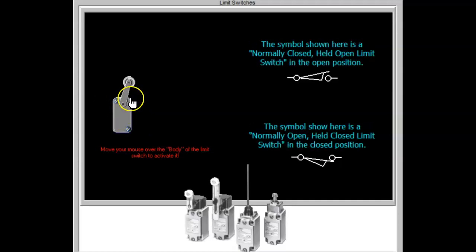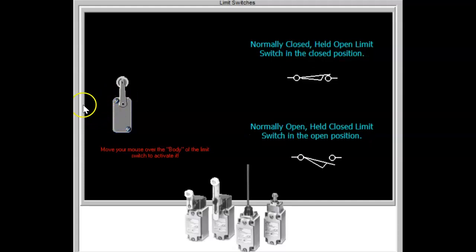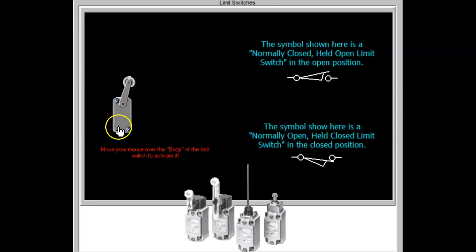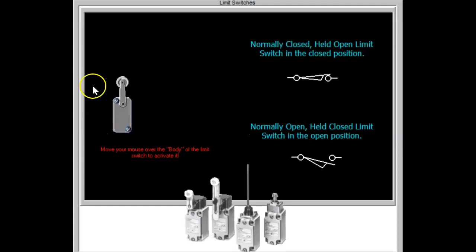Generally, the operation of a limit switch begins when the movement of the machine or a moving part of the machine strikes an operating lever that actuates the limit switch. The limit switch in turn will affect the electrical circuit controlling the machine or a portion of the machine. Limit switches are pilot devices in the control of magnetic starters and relays. Their function may be to start, stop, reverse, slow down, or speed up the electric motors that operate the machine.